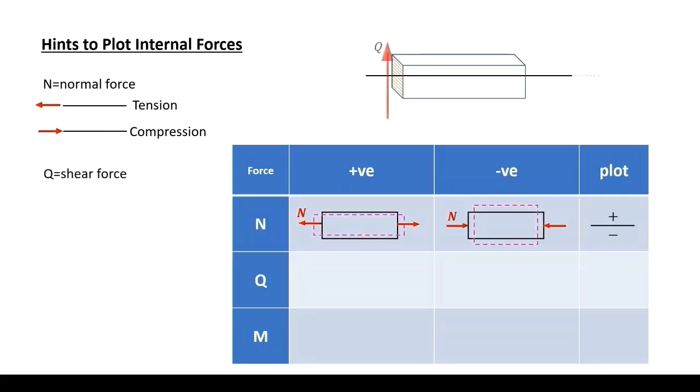Shear force. A shear force is in the direction of the cross-section, in other words, parallel to the cross-section and perpendicular to the center line of the beam. Our elemental beam, direction of positive shear, and the deformed shape of the beam under positive shear. Consider the left side of the beam. Positive shear is an upward force.